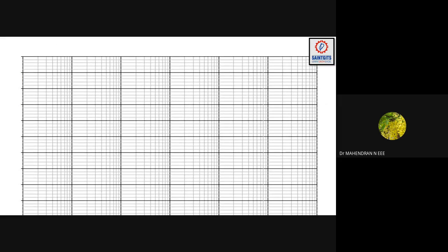So we have to plot this. The x-axis is the log omega scale, always representing frequencies, and the y-axis is gain in dB. At the x-axis, gain is 0 dB, here it is 20 dB, and here 40 dB, then minus 20 dB, minus 40 dB per decade.